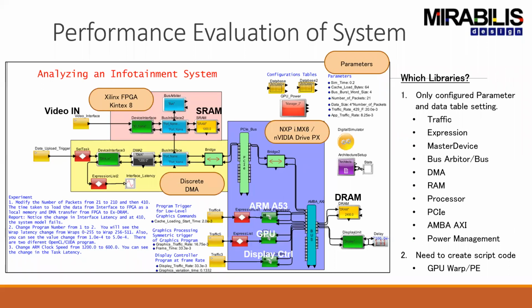So as you can see here, it's not just about the SoC, not just about the software, not just about the interfaces, it's putting the entire system together, including the power, which is a major attribute in this particular design. So only when you have the entire end-to-end design can you actually look at the quality of my particular memory controller algorithm.